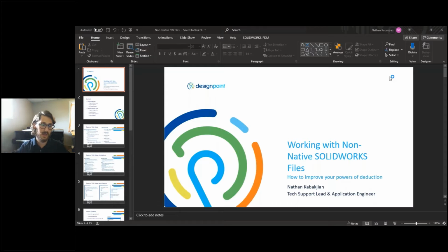So for types of CAD data, types of 3D CAD data, these are just a smattering of them. Now this is everything organized in order of preference that SolidWorks likes pulling into it. Now there are things beyond this that SolidWorks could utilize, but if you've ever worked with Parasolid models, STEP models, IGES models, looking at this from a hierarchy of preference as they import into SolidWorks tends to be helpful for two reasons.